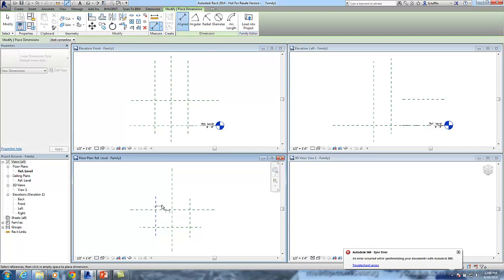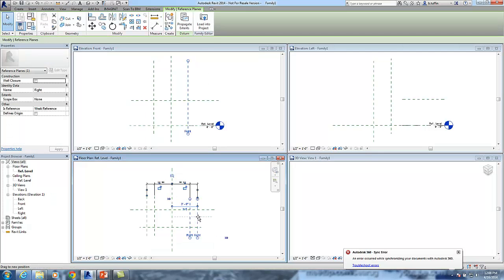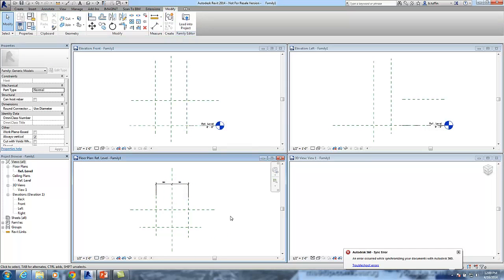So right off the bat, I'm going to come in and assign a couple of simple constraints. An equal constraint here. Generally speaking, I know an equal constraint is a pretty simple constraint to apply to an object, but best practice is going to be to assign a parameter. Once you've assigned that parameter, test it. There's nothing worse than building 10, 15 parameters in your content and going back and trying to adjust it and finding out the whole thing blows up. Usually you're better off just erasing everything and starting over. So once you create a new parameter or constraint, always flex your content.